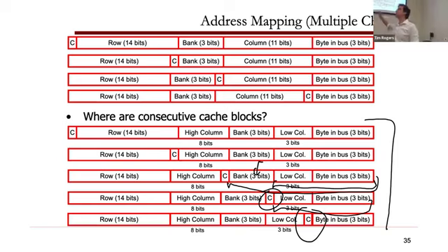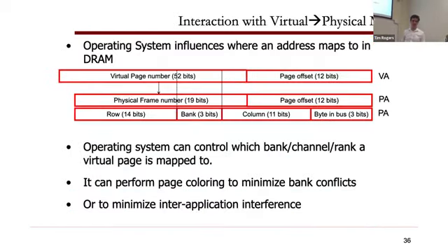So the more parallelism, the more in-flight memory accesses you have, the better off you are moving the channel bit further up in the mapping stream. With fewer accesses, you kind of want the channel bit further down because you have less stuff to play with. Thankfully for GPUs, we have lots of accesses, right? So we don't need to move the channel bit way down. It's usually further up in the address space because there's plenty of accesses to go around and you can light up the channels appropriately.